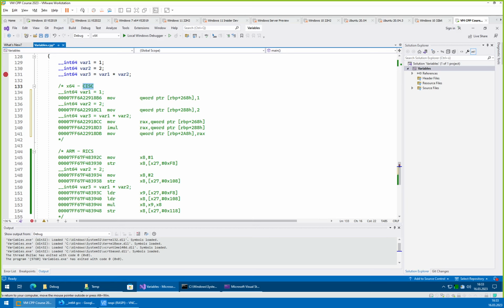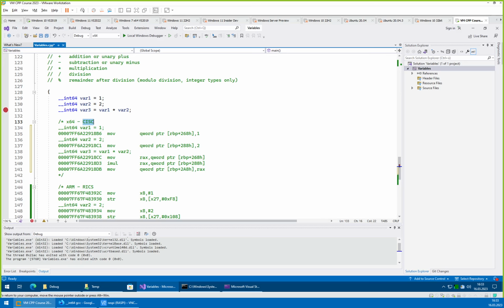Simply because you have a much higher code density. So on the ARM platform, every single instruction, no matter what it does, will always be 32-bit long. And if you have, for example, a lot of constant variables in your code, you will need to put them somewhere in your code and then jump around it. You cannot write very large 32-bit numbers into one opcode. So in the CISC case, in this move, we only used one, but we could have had here 0xFFF inside, and it would be just fine. On ARM, you can usually go up to a short at most.